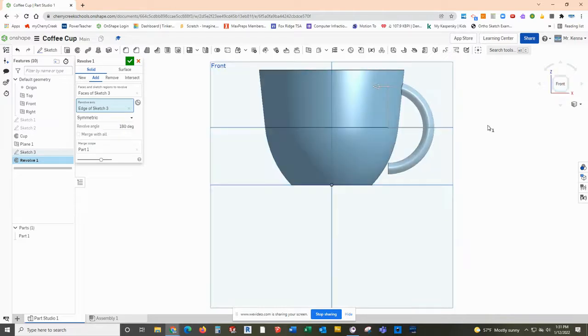Looking at it from the front view, I'm going to increase this number. Does 200 do it? It does. We kind of get in there. I'm going to do something like 210. How much I actually do doesn't really matter since I know I'm going to cut the inside out, but that does give me a nice idea that I am all the way in. I could even do something like 270. One of the other options that's pretty useful is this 2 directions one. In this direction, I am going to go 90 degrees.